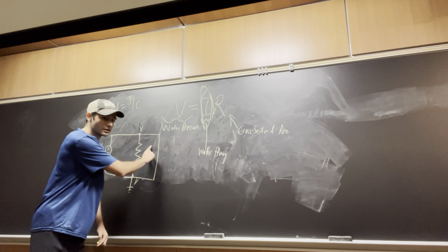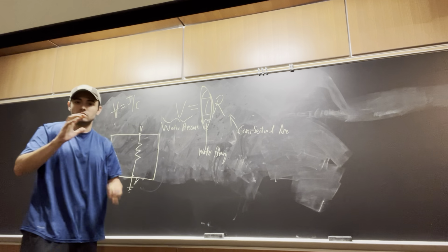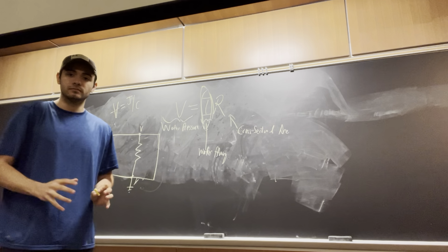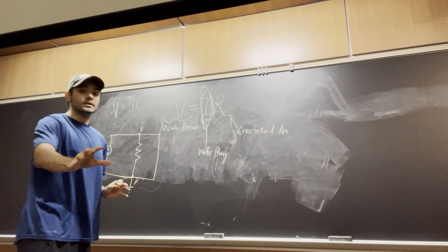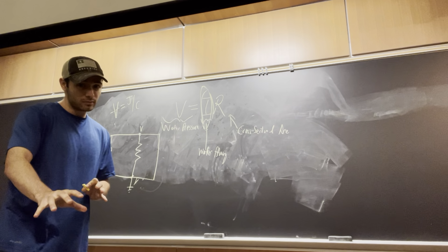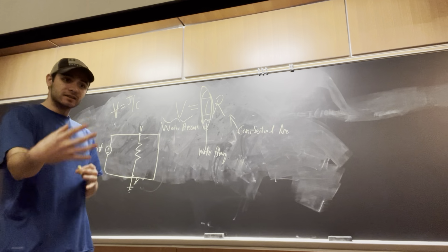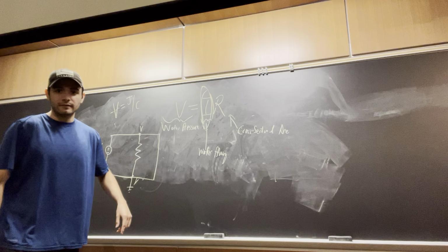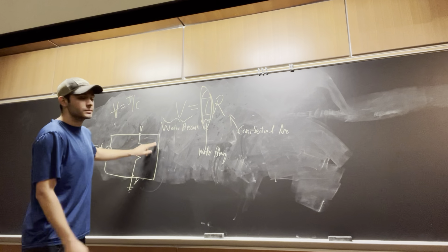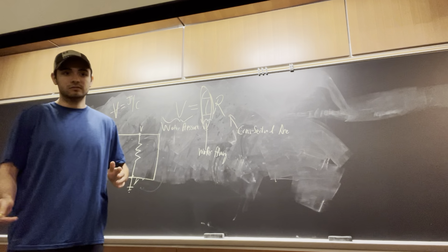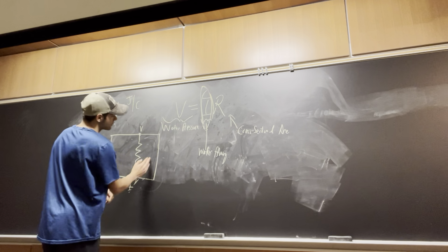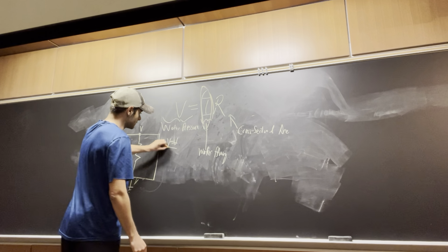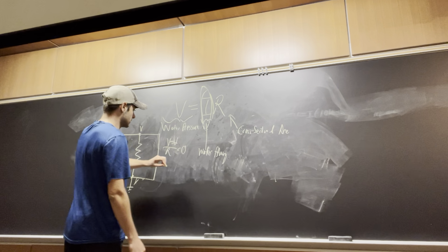We're assuming this is a low frequency DC problem. You might correct me, if we're in a high frequency problem where parasitics occur, AC alternating current, this wire has resistance, then this is actually not true. With skin depth resistance, that's going to be different. There is going to be a voltage difference. But at the end of the day, we're treating a wire as just a wire. There's going to be no difference at all. There's going to be V minus V divided by whatever R, which is going to be 0.